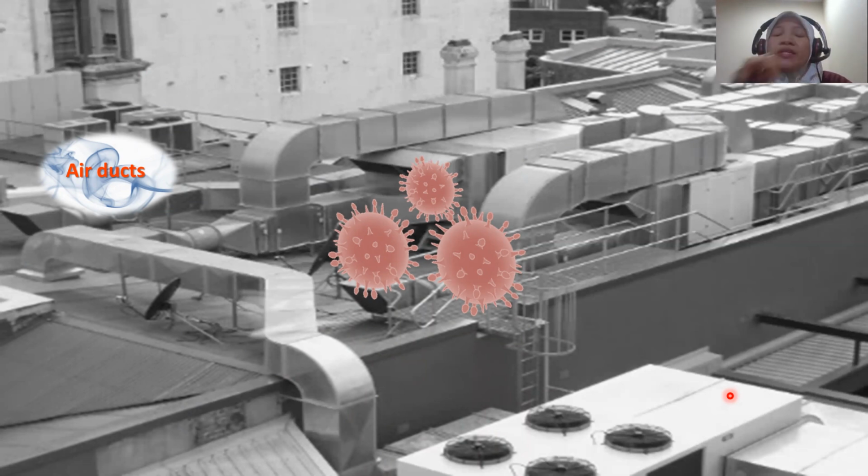And if the air duct is also not maintained properly, because normally there is a periodic maintenance schedule in order to change the filter, and sometimes you need to clean the air ducts, if the maintenance is not done as scheduled, air ducts may provide hazards to the air and to the factory.